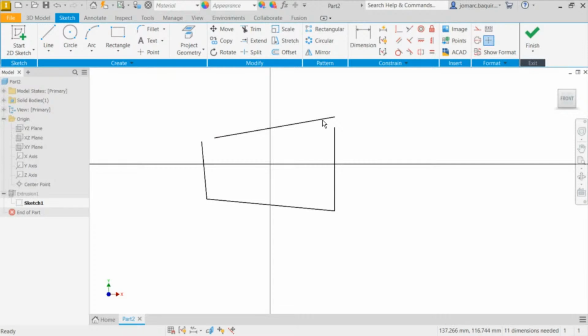And by default, in Inventor, it adds constraints. And those constraints are initially turned off. So if I hit F8 and F9, again, F8 is for the constraints to be visible, and to turn off their visibility, it's F9. Okay, F8, F9. So notice here, if I select F8, automatically one of the lines that I have created is a vertical line with a vertical constraint.